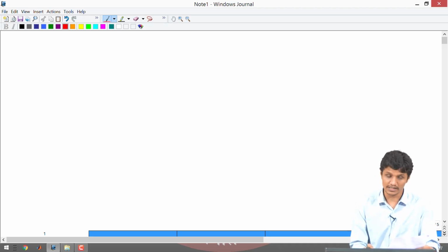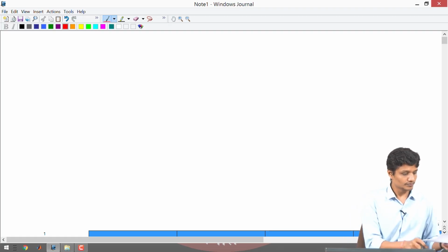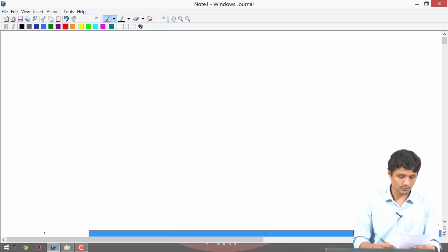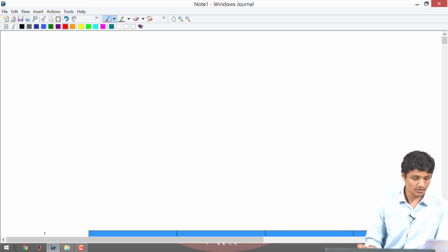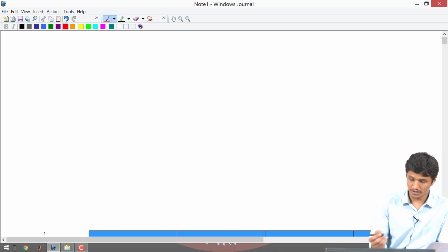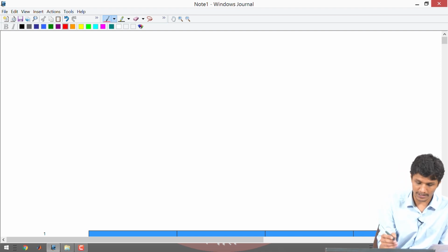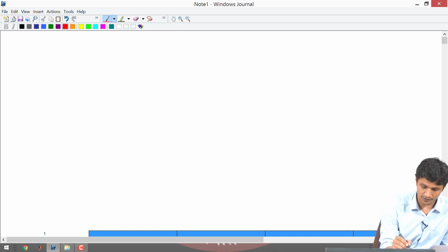In the question they have mentioned that the pressure drop is constant throughout the process, and the pressure drop is 46194.8 Newton per meter square. So first I am going to convert all the data into one unit system. Here I am going to convert all the data into foot-pound system units. First I am going with the area, the filtrate area.